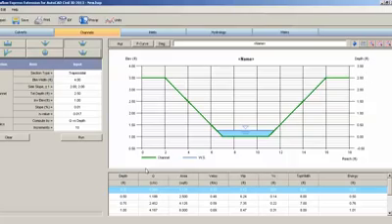There is another table at the bottom showing the depth, the discharge at each depth, the area of section, the velocity, the wetted perimeter, the Y critical, which is the critical depth, the top width, and finally the energy.